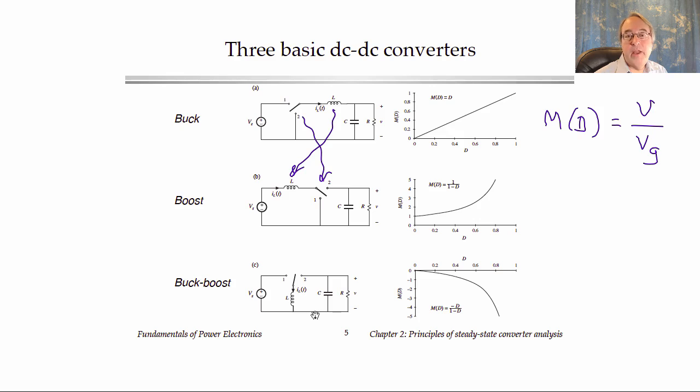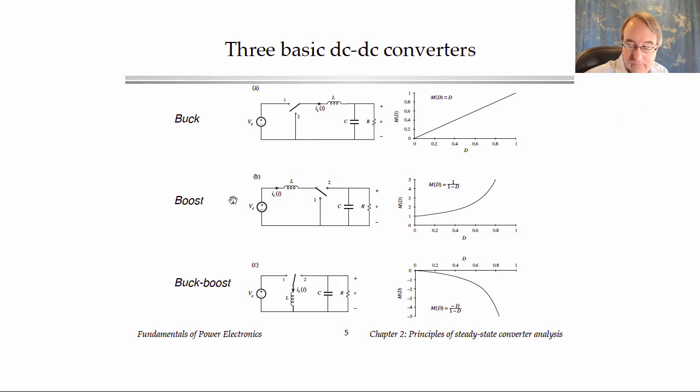In fact, there are many converters known. We can build a converter by some circuit containing L's and C's and embedded switches, and change any voltage into any other voltage we like. So we found the output voltage of the buck converter using these arguments of Fourier analysis and low-pass filtering.